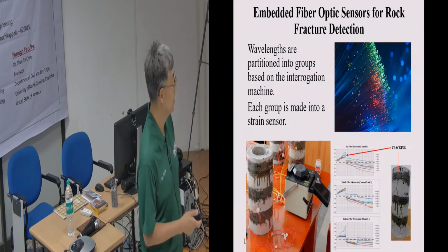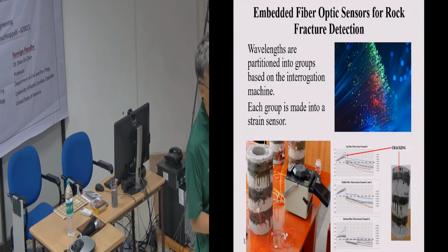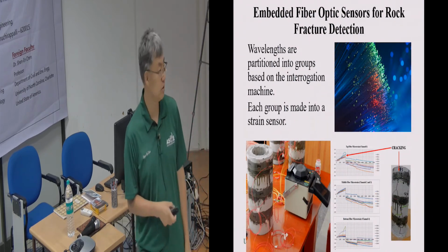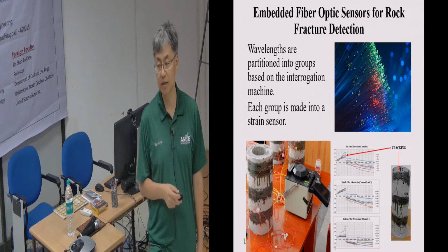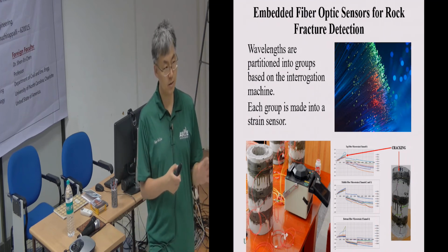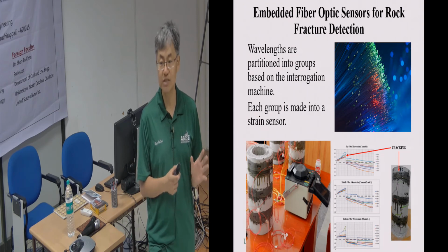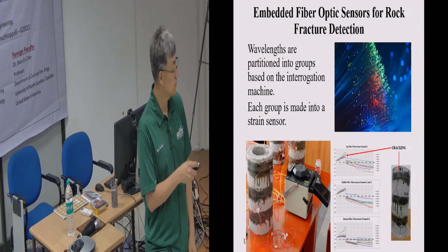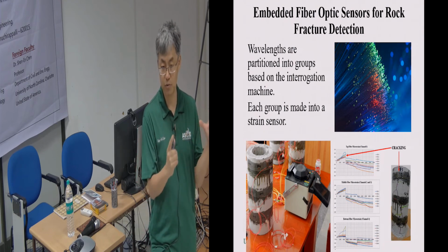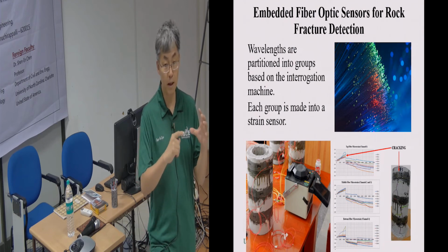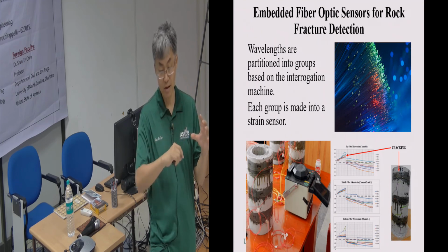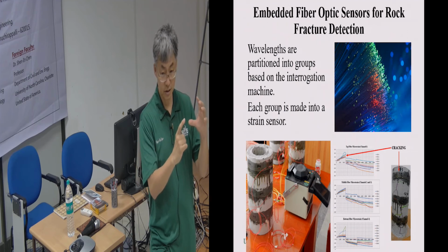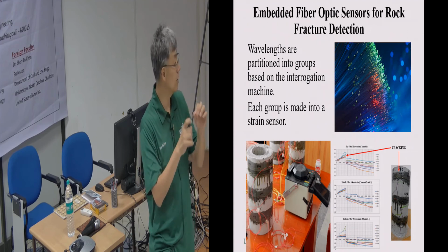So, anyway, the last slide I wanted to show is the fiber optic technique. There are certain applications where you really have to use a technique that can give you more precision. In this particular application, you see those cylinders. We are studying how concrete pipes crack. Concrete pipe cracking is random, right? But if you have fiber optic sensors that you tie around, those fiber optics act as strain gauges.